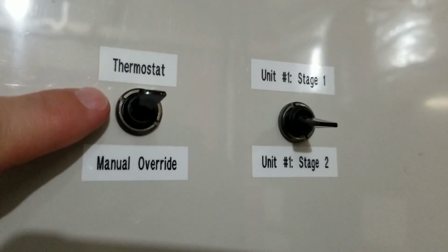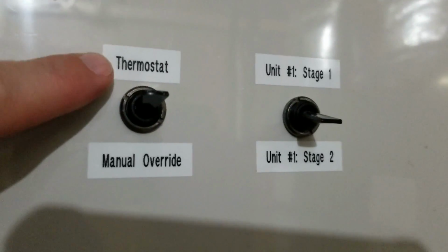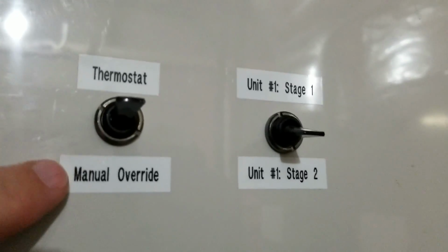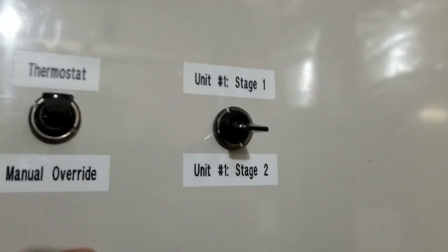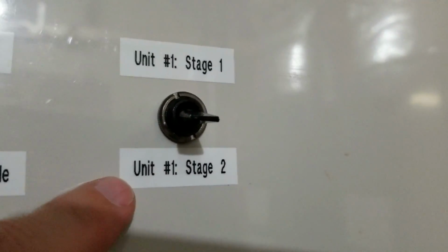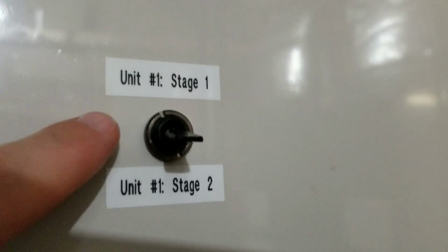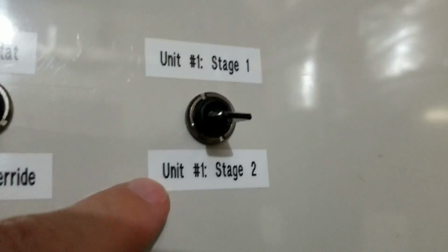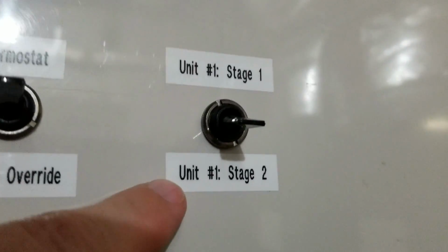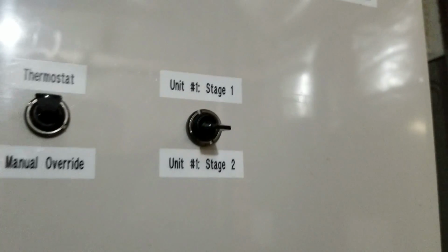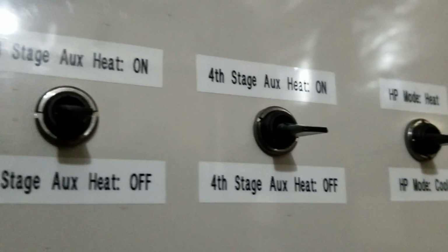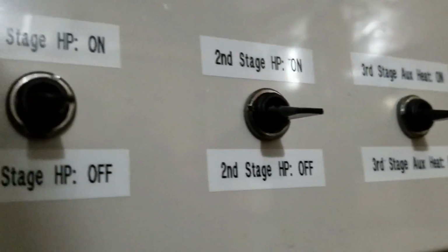So this switch is used to switch the whole system from being commanded by the thermostat to being commanded by the manual override system, which is just a bank of switches that's here in the box. This is good if you need to just disconnect the thermostat and run some tests. Then this switch actually swaps which unit is stage 1 and 2. So up here, that means HVAC unit number 1 is stage 1. Down here, it means HVAC unit number 1 is stage 2. That's good so you can swap it periodically based on the hour meter status so that one unit doesn't do all the work. Down here along the very bottom are just switches for controlling the various things that the thermostat automatically controls that you can control when it's in manual override mode.